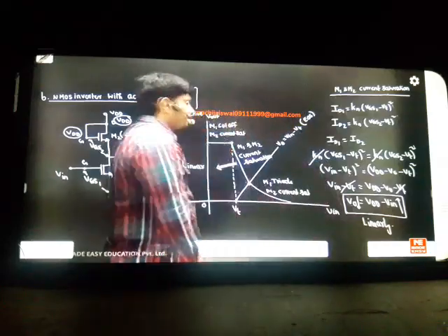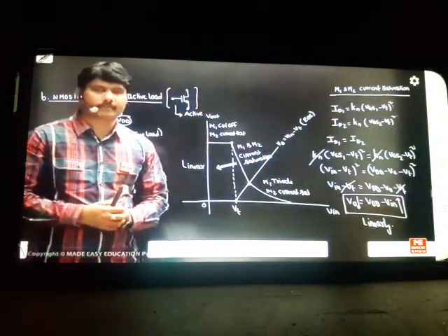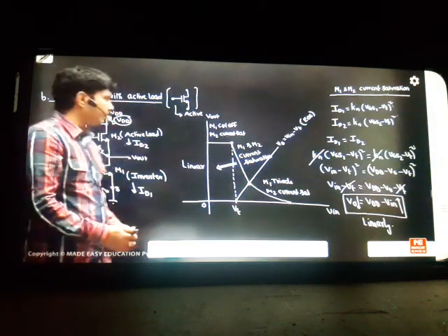So this is the background proof for you. Why is it falling linearly? This is the small mathematics for it. It's not falling like a parabola, now it's falling like a linear line. VDD minus VIN is equal to V out, meaning as the input increases, your output will linearly decrease. So this is the concept behind your second topic.